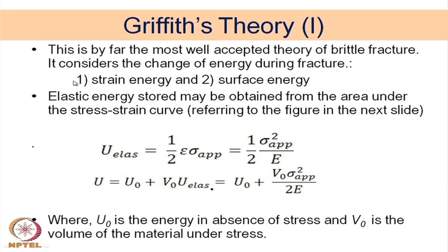Okay. So, there are two different terms, one is the strain energy term, and that is the change of energy during fracture, because you are applying external stress, and that stress is generating some internal strain energy. Even if the fracture is not there, the strain energy term will be there, because you are trying to pull the atoms. So, the neighboring atoms are being pulled from one another, and therefore, the bond length increases.